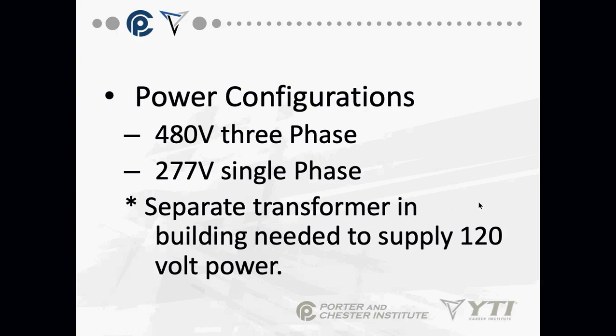Now, if it's the 480 three-phase, it'll never be the Delta configuration, correct? I don't want to ever say never, but most often. Why don't we say that 99% of the time? So it's a pretty good assumption that 480 volt means non-delta. That's the assumption I would make.